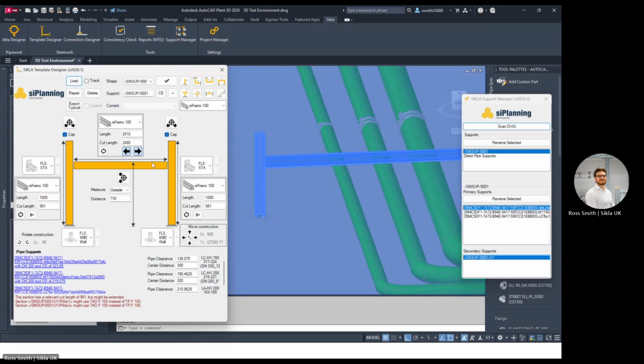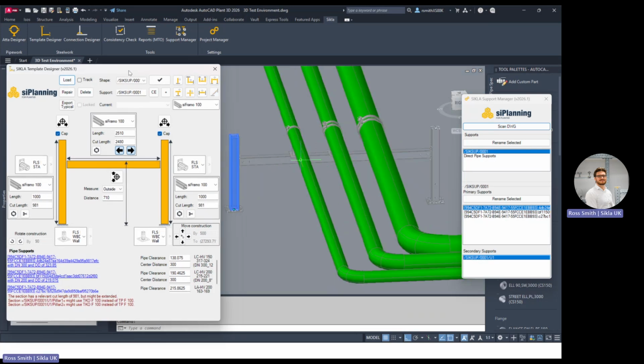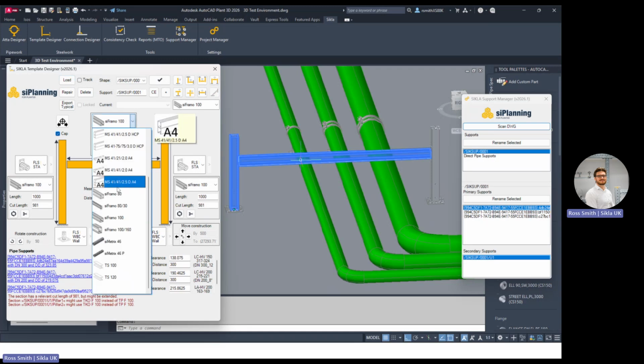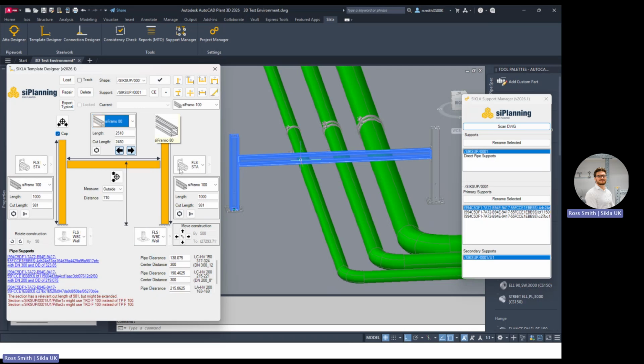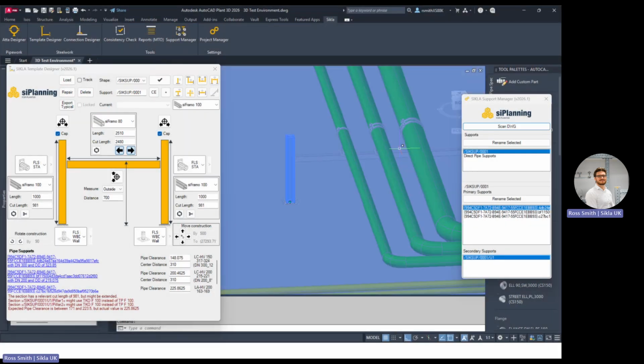Okay. If we need to have a hybrid frame using 1, 2 or more profiles, let's say we want the columns to remain as F100 and the crossbar to be F80. So I will just change in this instance the crossbar to F80. And we know then that will consequently change the end connectors to reducing connectors. So they'll change from 100 to 100 connectors to 100 to 80 connectors, okay? And how do I know this?